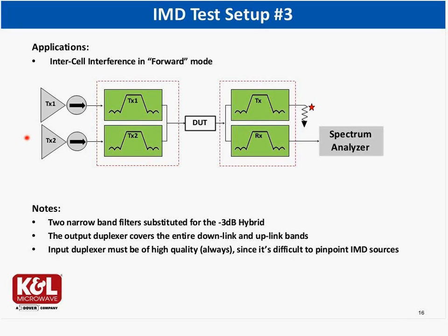The reason is that the filter is narrower band than a hybrid or an attenuator. I want to believe that this rate change is due to the extra delay the signals are going through. So I'm using the 2.2 empiric value and I found it to be quite accurate, but it's an empiric number.